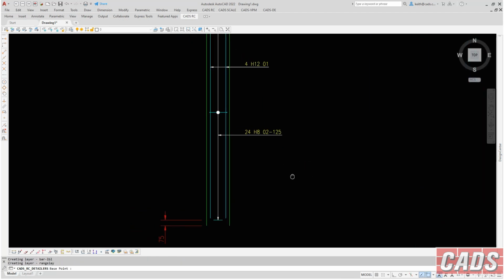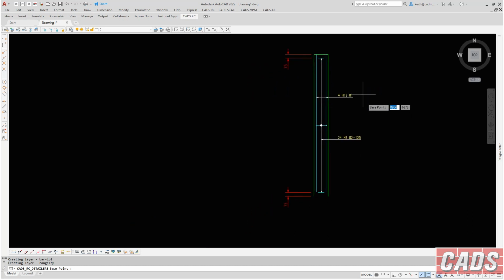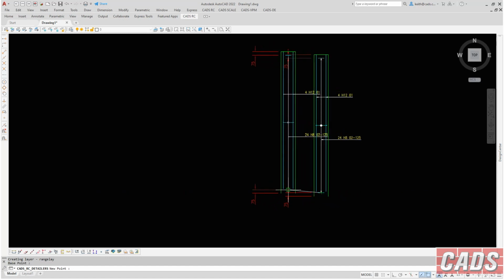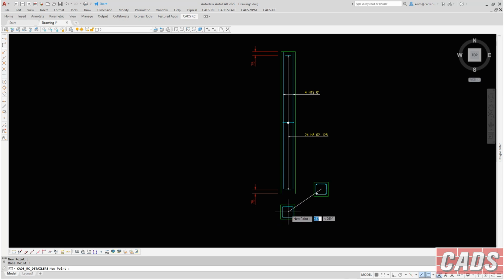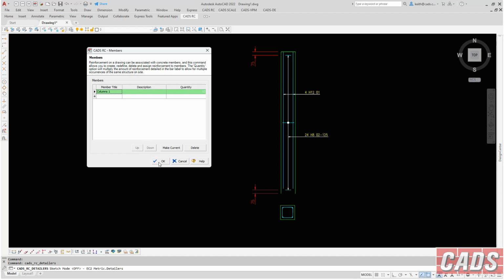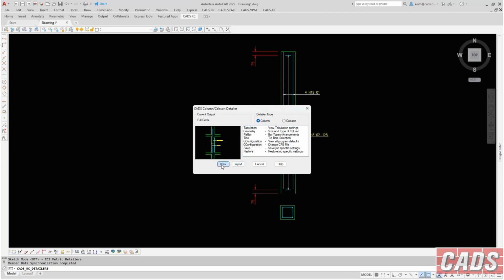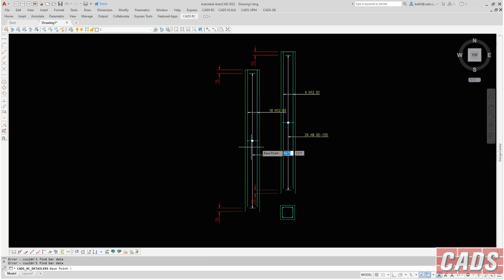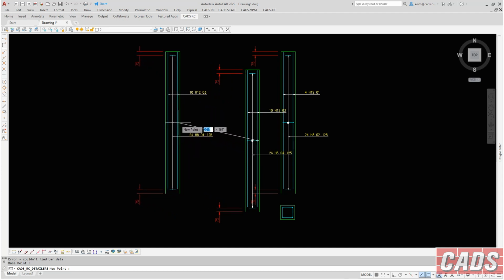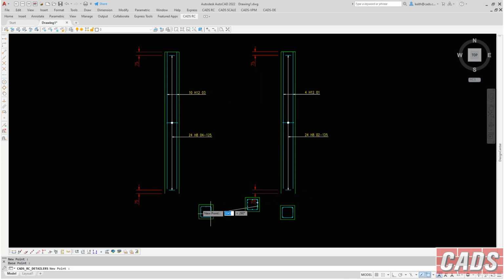And you can see the detail we've got there. Remember the 12s for the slightly smaller reinforcement requirements, and we can move that to wherever we want it. And then we get a section, and we can pop that down the bottom. Now let's just go back to the column detailing command, and we'll bring in one of the others, number 4. Yeah, this has got slightly more bars in it. It's one of the corner columns. And again, we can just move that to position over here, and there you can see the extra rebar in section. There we go. So that's the 2 column sizes that we had from the design. They're all detailed up now and labeled.